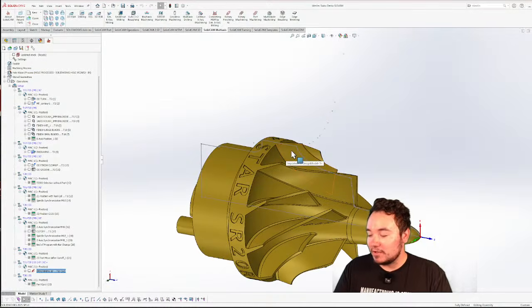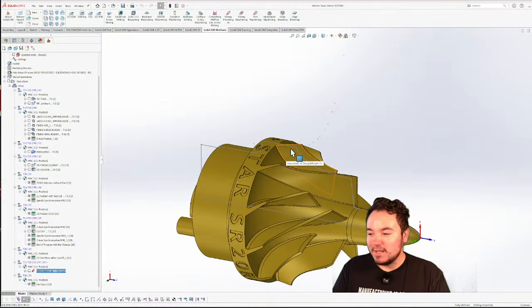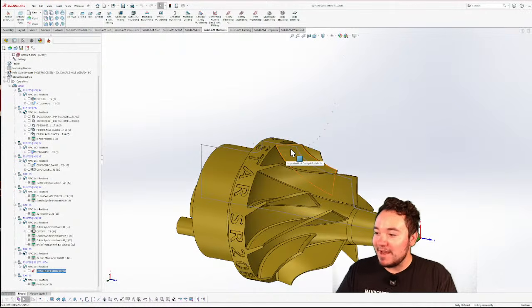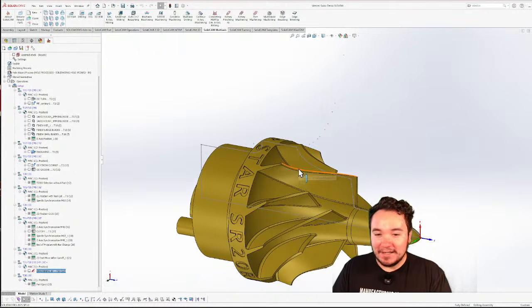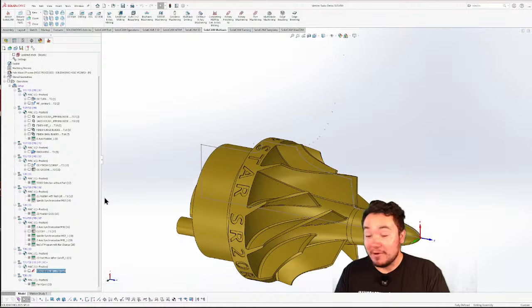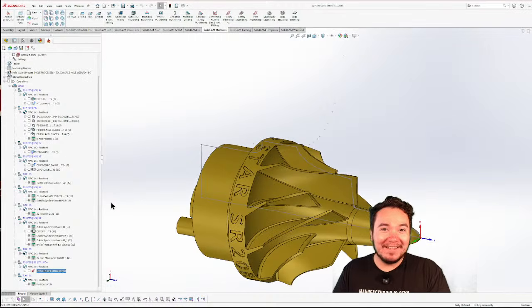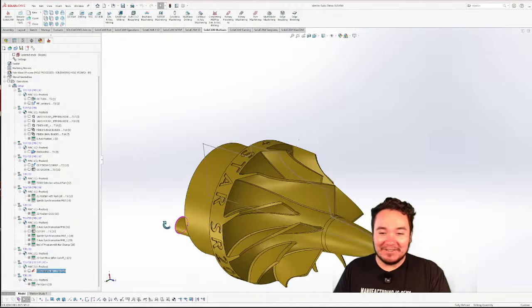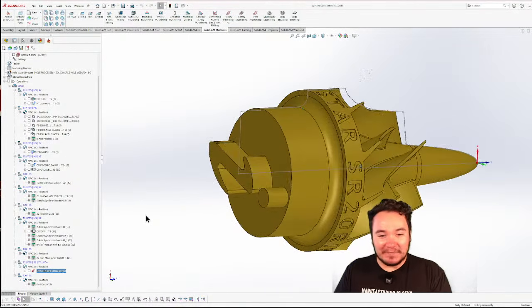But again, this is just a show part, and you get to see probably a lot more of the B-axis rotation with a ball end mill because it's trying to stay away from gouging. With the lollipop, you could just send it in there and almost do just a 3-axis toolpath because there's so much clearance around that ball. But again, just a show part, not a production part.